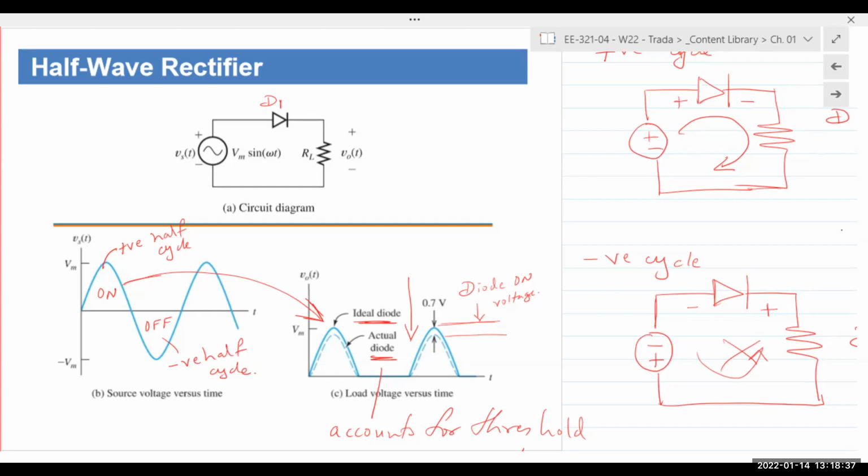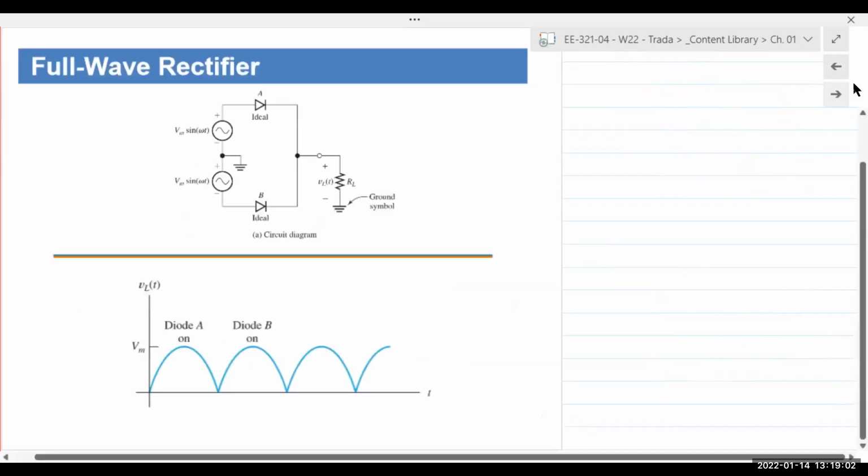So I've seen adapters where they would simply take the transformer out and, without a circuit board, they would just take diodes and twist the leads together and build a circuit in the air, kind of. You just take the leads, twist them, attach a capacitor, and you have a rectifier circuit. Well, those are the cheap ones. The really nice ones actually have a circuit board.